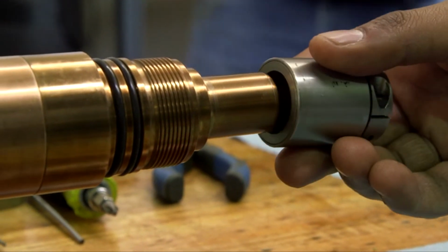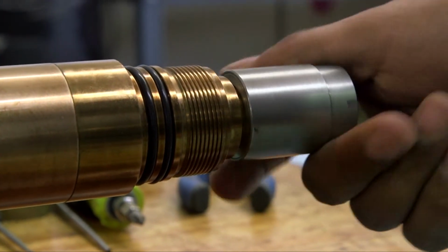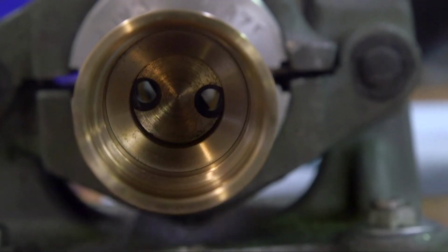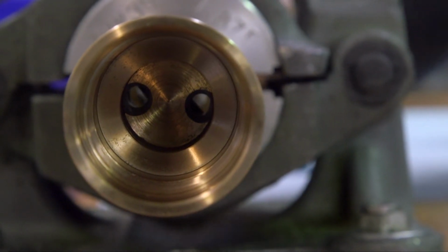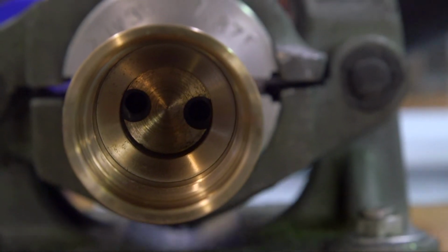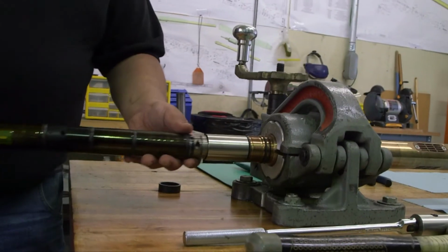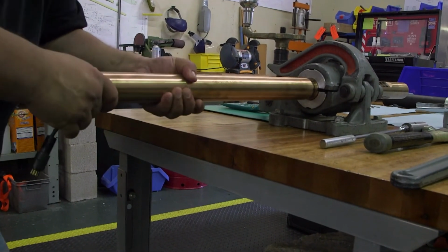The use of the magnetic coupling allows us to open and close the valve with all the critical high wear and, more importantly, the fragile components of the tool kept in air in a nice controlled environment, while the valve itself is in a pressure compensated environment. At this stage, the drive shaft and valve components of the pulsar are ready to assemble to the electronics.